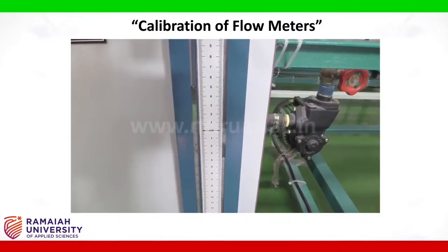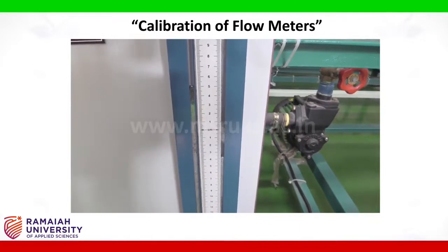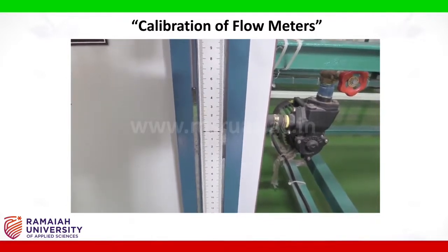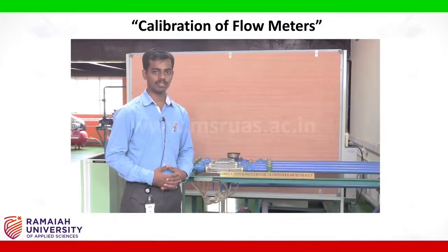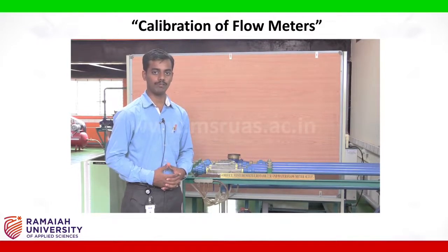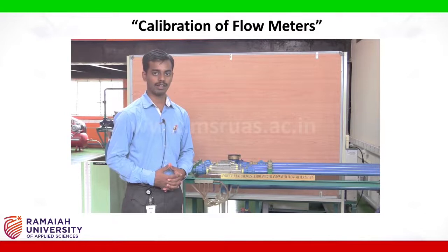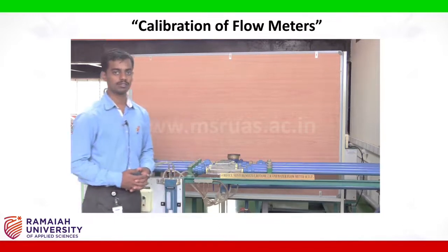The corresponding reading on the orifice meter can be measured by taking the values on the manometer of the mercury column. The same procedure is repeated for 4 to 5 different flow rate readings, and then after taking down the values on the rotameter and the orifice meter, let us stop the pump.